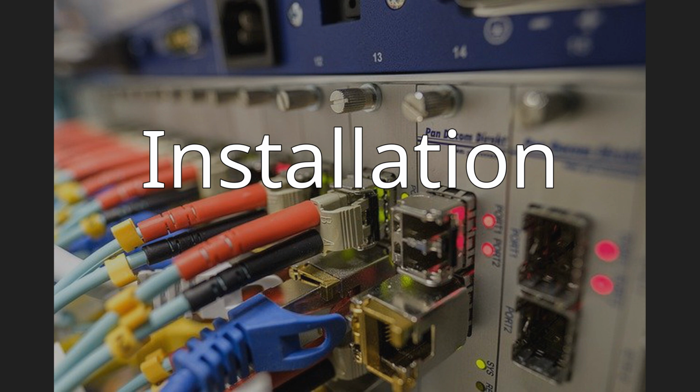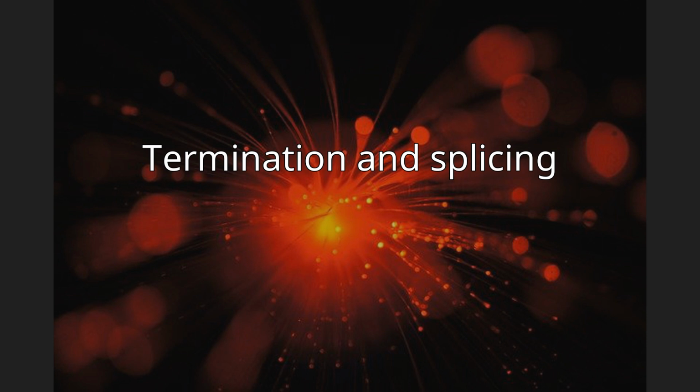Termination and splicing. Optical fibers are connected to terminal equipment by optical fiber connectors. These connectors are usually of a standard type such as FC, SC, ST, LC, MTRJ, MPO, or SMA. Optical fibers may be connected to each other by connectors or permanently by splicing, that is, joining two fibers together to form a continuous optical waveguide. The generally accepted splicing method is arc fusion splicing, which melts the fiber ends together with an electric arc. For quicker fastening jobs, a mechanical splice is used.